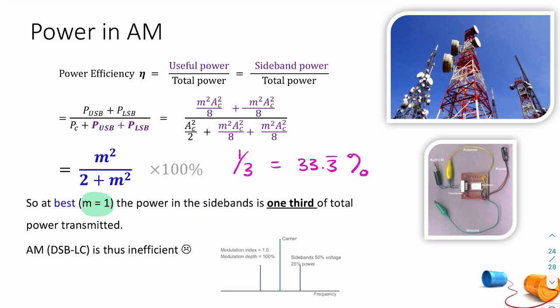But remember when we spoke about trade-offs in the design of communication systems? Power at the source, so at the transmitter, is readily available. So there's plenty of power here. So this is a radio mast with all these antennas, but power is available here. It's at the receiver where there is no power. Okay, so remember we looked at the foxhole radio, we're looking at an envelope detector with no power. There's all passive components, there's no local oscillator, there's no power supply. So this is a version of that, okay?